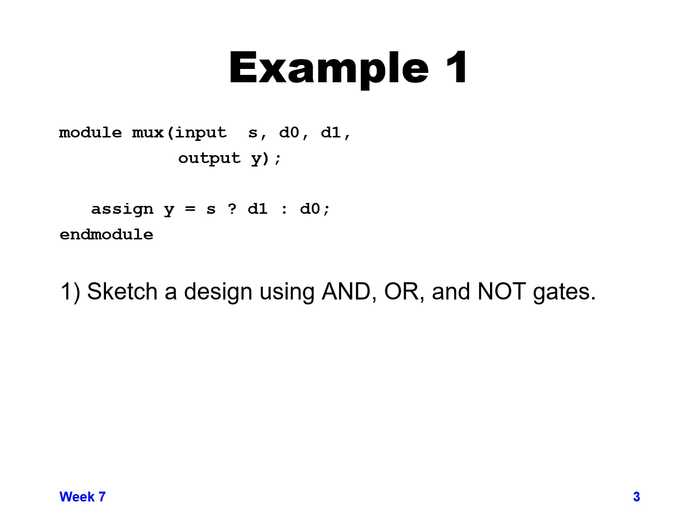Let's start this week with an example of creating a more complex logic gate. So up at the top of the foil here is some RTL or Verilog code for a mux function. So we have three inputs. S is our select, D0 and D1 are our data inputs, and our output is the value of Y.